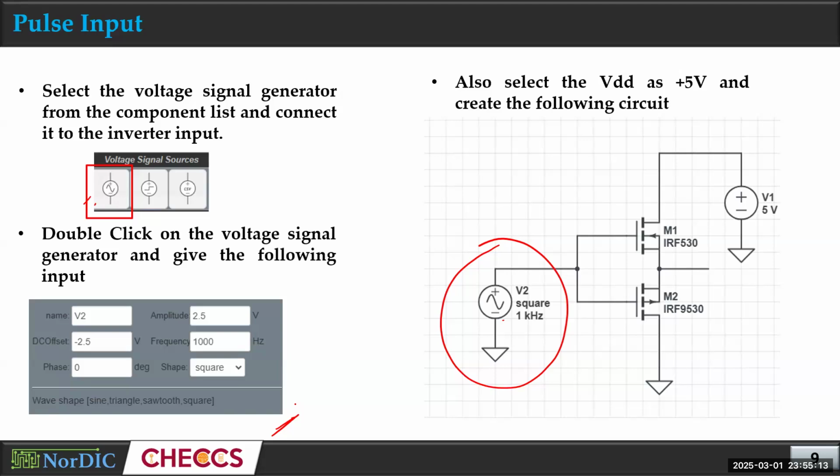Are we done up to this? Okay. We have applied the input and you have put in these values here, right? From the table. Then we have to do one more thing. This is the voltage source, right? From the DC source option, just double click on it and change the value to 5 volt. I think it was initially 1 volt. So change this to 5 volt, and then you will have this circuit that's shown here.